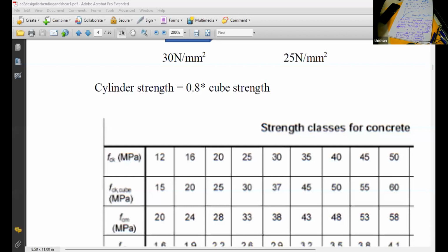Even with pre-stressed concrete members, because you might be using various chemicals on the road, and vehicles also drop various chemicals. And in coastal zones, there may be chloride attacks. All those can be very well controlled if you are using 15% fly ash in pre-stressed concrete members. So the reason for using fly ash in pre-stressed concrete is actually it's detrimental, but if you are interested in reducing the chloride attack, then using 15% fly ash is highly recommended. So for each thing, there is a different reason.